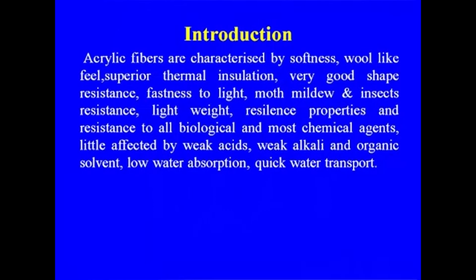Acrylic fibers, why the importance of the acrylic fiber? Because it has a specific property, an appearance like wool, which I showed in the picture, how it looks. This is just like a woolen material. So acrylic fibers are characterized by softness, that is the basic requirement for a wool-like feel, superior thermal insulation, very good shape resistance, fastness to light, and moth, mildew, and insect resistance, because these are some of the